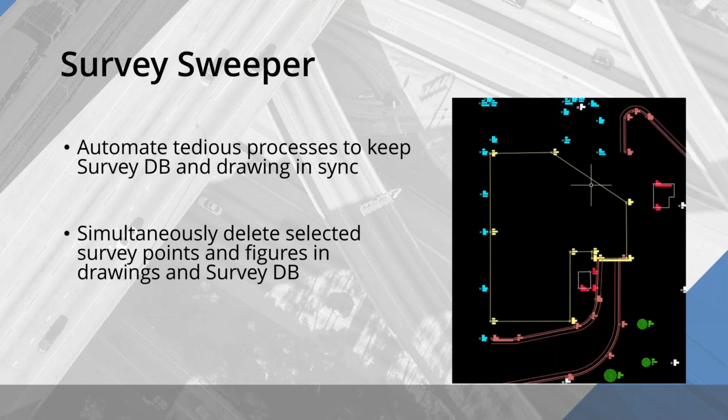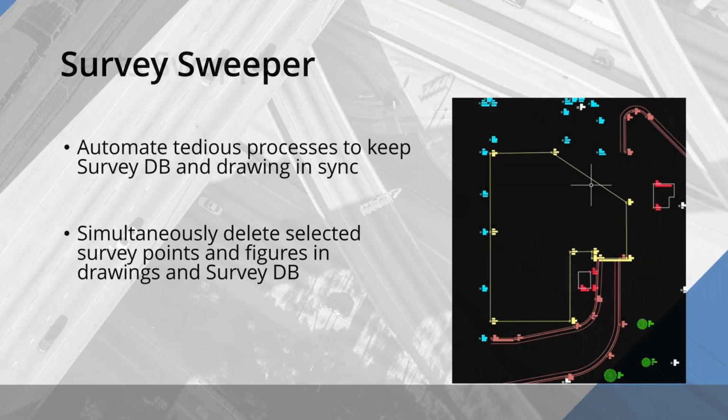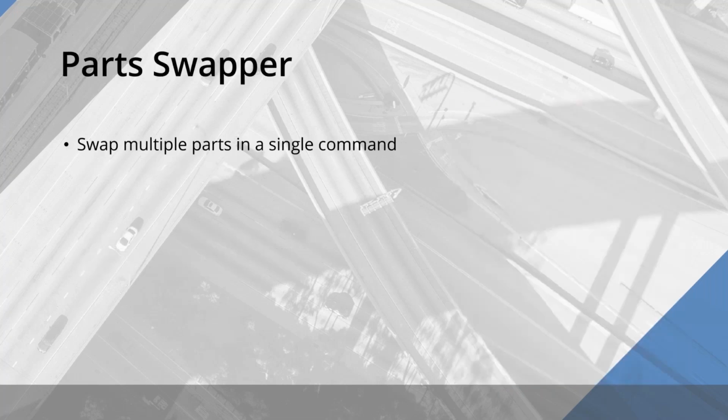It's fairly straightforward, and I'll show you this firsthand. When you're working with databases and perhaps massaging or fixing up a survey, you often get in the situation where you're creating duplicate survey figures, which is a really annoying thing. What this tool will do is help sync any of those deletions across both your drawings and database at once.